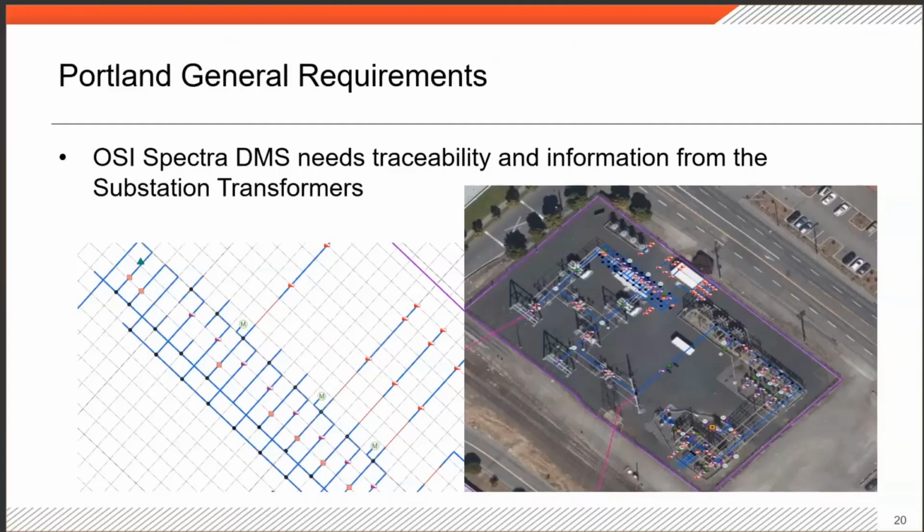In this project, although it was a geometric network digitizing project, we used ArcGIS Pro because you can apply grid lines at a proper angle. You can rotate those grid lines so that we could supply equal spacing between devices, even when the substations were not oriented in true north. This rotation of the grid in Pro allowed us to place those things in very neatly. Some of this spacing is totally required for getting in SCADA elements and stuff like that between buswork.